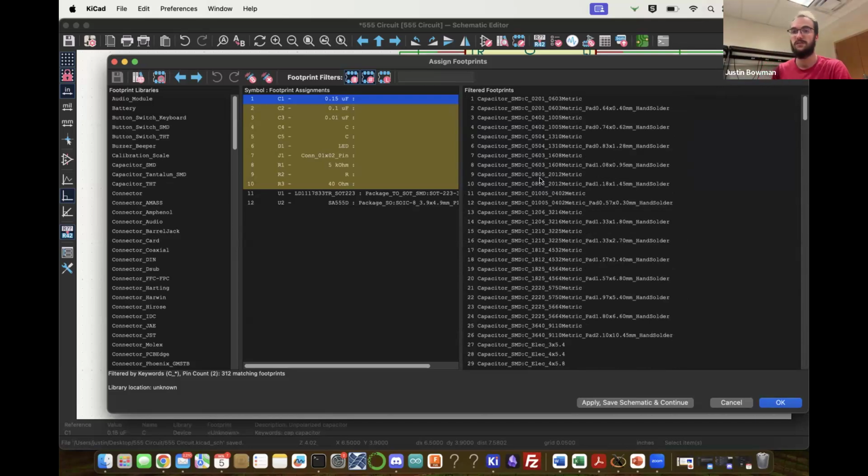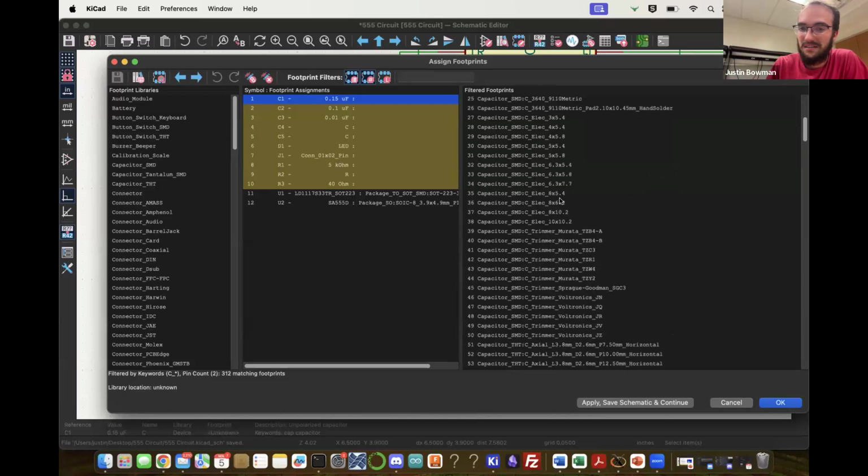Yes. So if you want it through hole, we're deciding how big of a capacitor and what type of capacitor at this stage. So we're deciding on the size. Obviously, the larger the size, the easier it would be to do the work by hand. So say we should go with through hole because it's easier to solder.